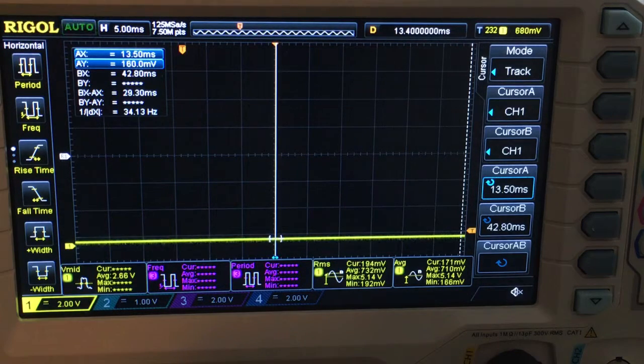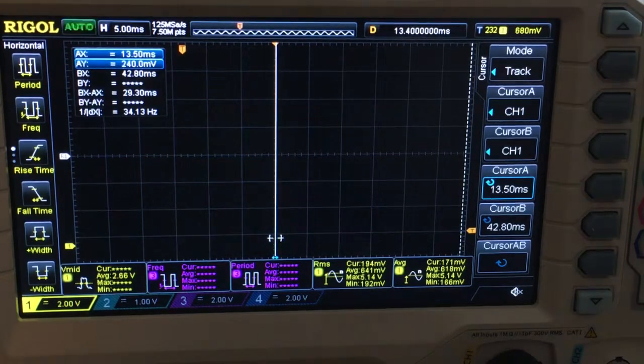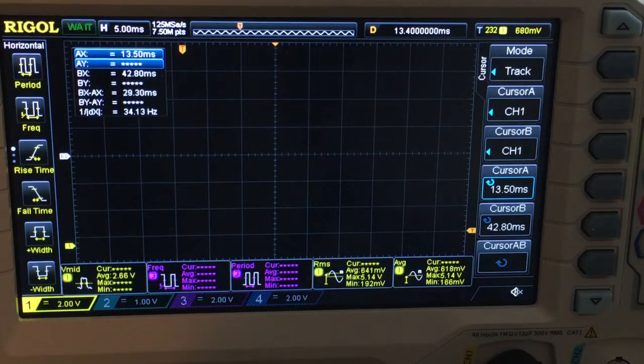Now, let's look at what happens in a real event, if I'm running a camera and I want to do something at high speed. If I type these things in or click on them, they're not going to be very fast. However, during an acquisition at high speed in a sequence, I can run a pre-programmed command. In this case, I'm going to run a command that will give me a 30 millisecond high and low pulse. Okay, and that ran so quickly we didn't get to see it. So I'm going to set my oscilloscope up for one capture, and I'll run it again.